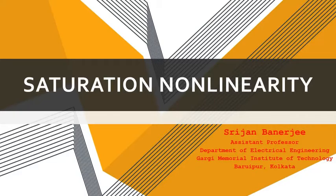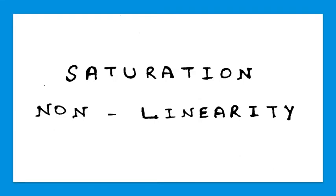Today I will discuss saturation nonlinearity. It is a very common type of nonlinearity. This kind of nonlinearity we can mainly observe in the magnetizing curve of a DC motor. In the magnetizing curve of a DC motor, we can see linear behavior initially, but after that there is a saturation in the curve which introduces nonlinearity in the system.